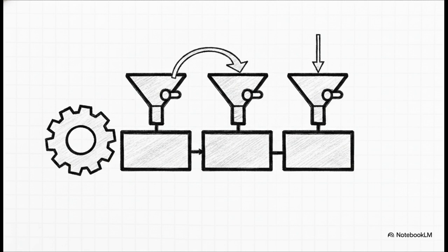choice. If our selector signal is set to 0, the multiplexer pulls data from the preceding flip-flop, running smoothly in shift register mode. But if the selectors flip to 1, the multiplexer grabs an external input, allowing us to parallel load fresh data all at once. And because this is a sequential circuit wired perfectly with non-blocking assignments, absolutely every single action occurs dependably right on the positive edge of the clock.